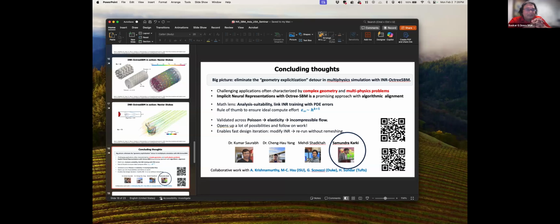Great question. I think I can answer this, but Guglielmo Scovazzi has already shown that, right? So essentially, that's the reason why you do the Taylor series not from the true surface, which can have sharp corners, but from the surrogate surface, right? And then all you do is you take Gauss points on the surface and find out the closest point. The key thing where it'll break down is if the closest point is too far away, right? And the error, like I showed, scales as d, right? And so the further away you are, the worse it gets. And that's why adaptive meshing is super useful, and that's why adaptive octrees are super useful. You can adaptively refine arbitrarily to get close to the true surface.